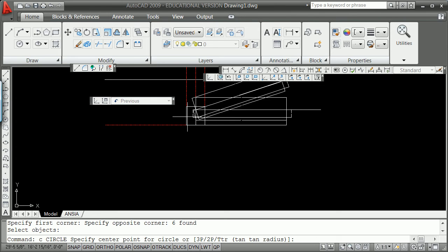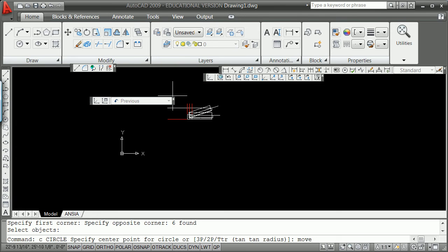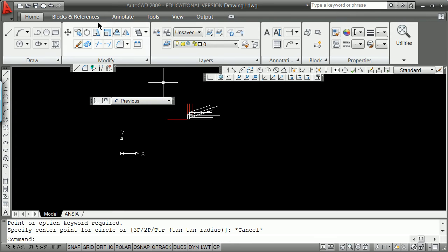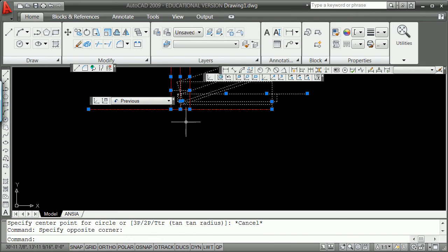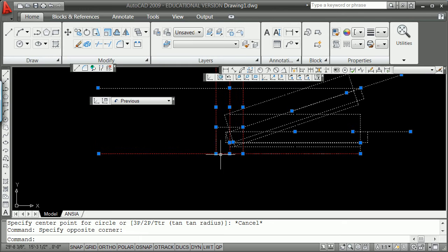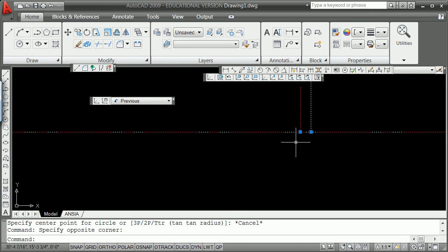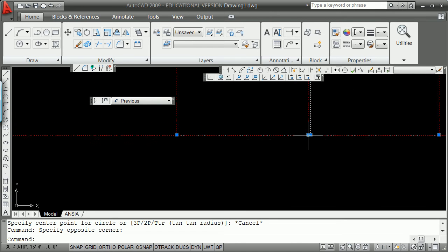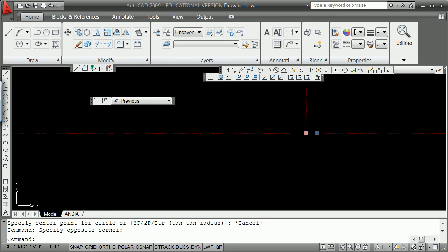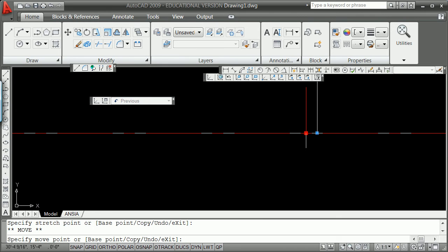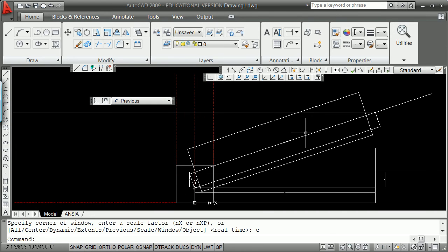So I'm going to go ahead and move, if I would. I guess I could grab everything, right? I could go and look for that node point, which is right here. Spacebar, move, and then give it a point of 0, 0, 0. Zoom extents. There we have it.